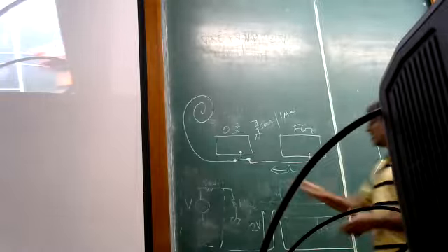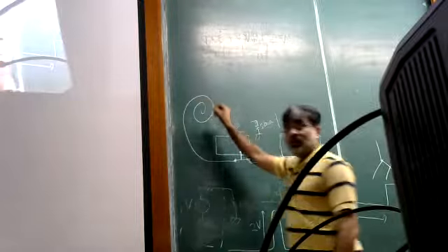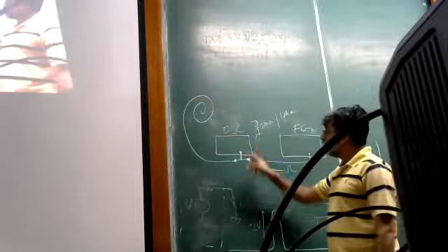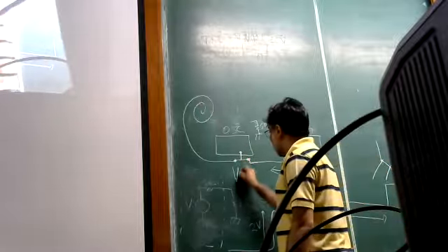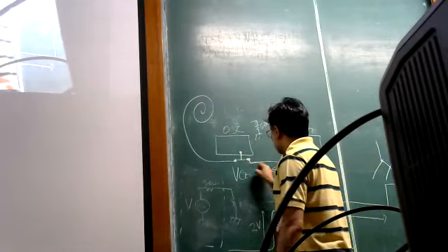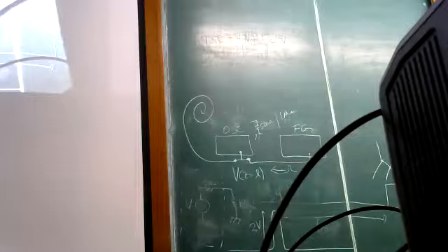If you imagine this whole thing as a single continuous transmission line, this T's job and the oscilloscope's job is for you to measure the voltage at this particular point, z equal to L, the length from here to here. So what do you expect to see? In some sense, this is now behaving like an ideal voltage tap at that point. It's not participating in the actual transmission properties. In some idealized sense, there is always something going to happen, but it's good enough for this.